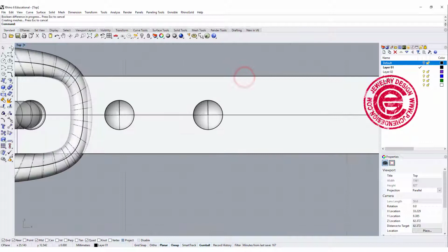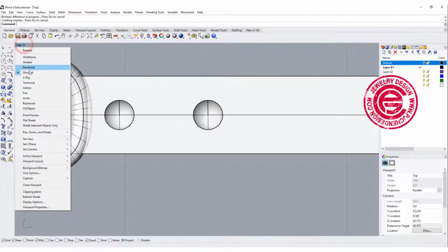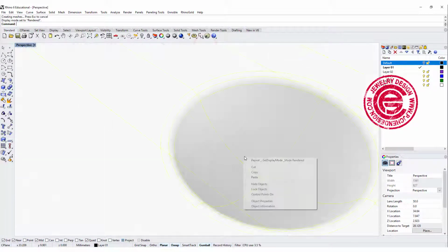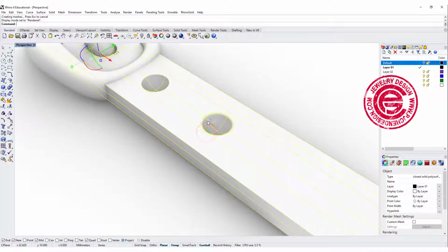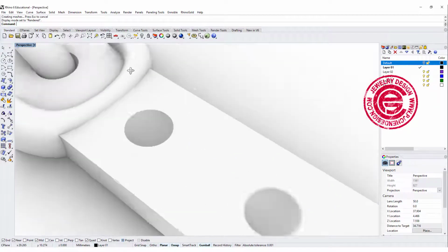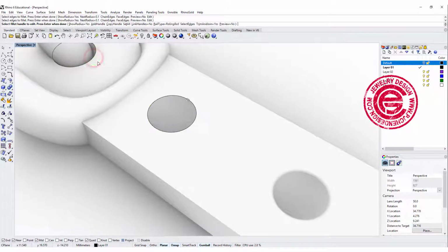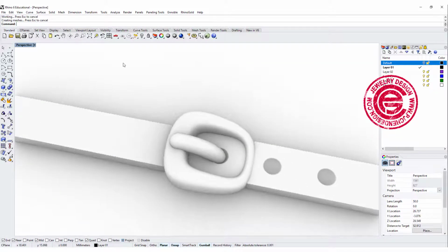Okay, when you look at the render, it might not look good with the harsh edge there. So what I would like to do is give a little bit of fillet, and let's do something really small, maybe 0.1. It just looks much better on the rendering, as you can see over here. So for the comparison, you can see this one is really nice and rounded, and this one just looks too machine looking. Let's go ahead and fillet this edge and also this edge as well. Okay, so they are all nice and rounded.